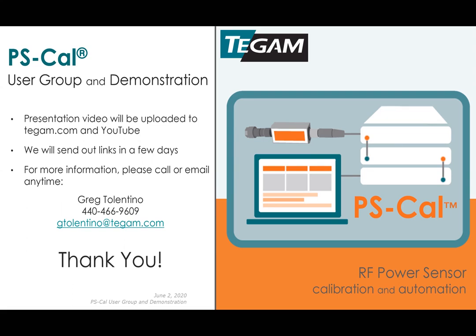I will say that our goal with PSCal is to actually take a different approach with it, and this will not be in the next release, maybe the release after. Our approach is going to be to use actually the 2505 as your 50 megahertz reference. So as part of the calibration, the 50 megahertz reference will be performed. What we hope is, first of all, it helps answer this question: do I need to do this disconnect and connect to the device under test power meter power reference?